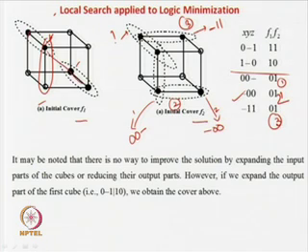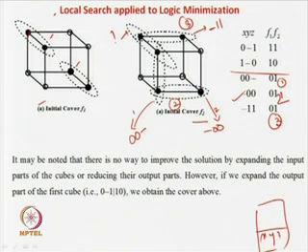But you cannot have a merger in between the diagonal part, because a merger in the diagonal part means you have to eliminate maybe 2 or more literals. This is just like a consensus. In case of consensus, if you remember the tabular approach, we compared something like x, y, z and x, y, z prime. We just compared between these two, because there was one bit difference over here. Similarly, it is very analogous in this picture.